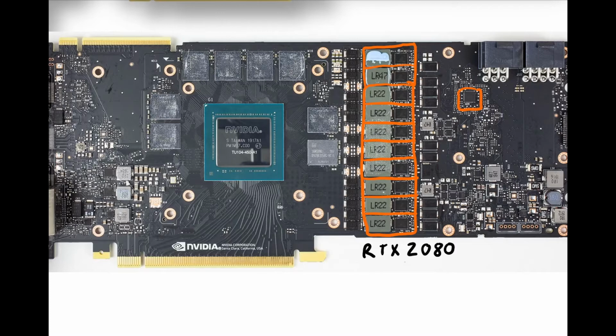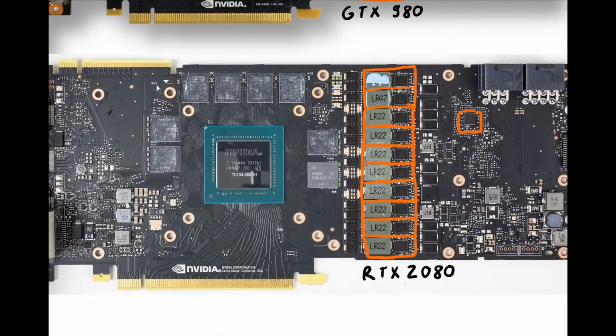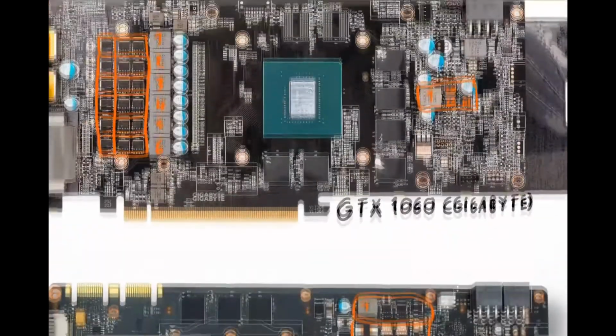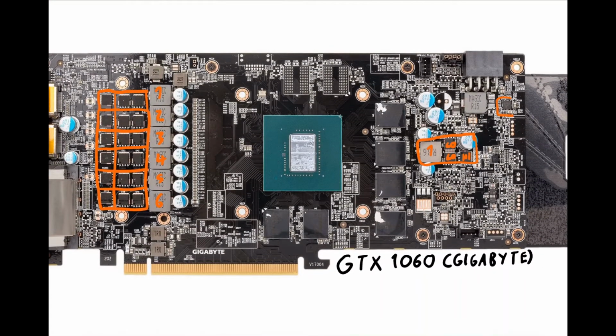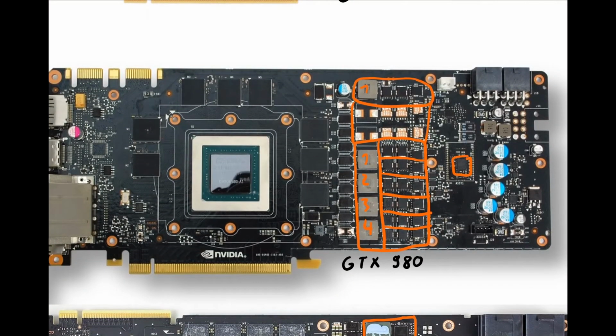What I forgot to mention is VMem obviously also has a PWM controller. That could also be the case on this card, that it's just the NCP4208 which also controls VMem. But most of the time you will have a second PWM controller, a really small PWM controller somewhere on the card. Like this could be it from what I've seen. This could be the PWM controller for VMem. So yeah, every VRM needs a PWM controller, obviously.